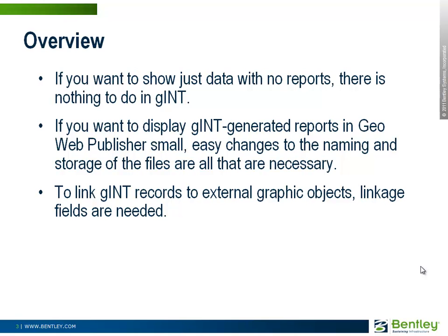So as an overview for gINT configuration, if you just want to show data with no reports, there's nothing to do in gINT. You're finished as soon as you type your data in. And once it's linked in to Geo Web Publisher, which is done on the Geo Web Publisher side, your data will show up as you want it to show up.